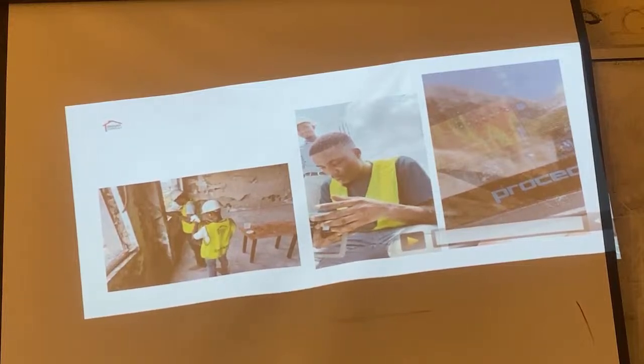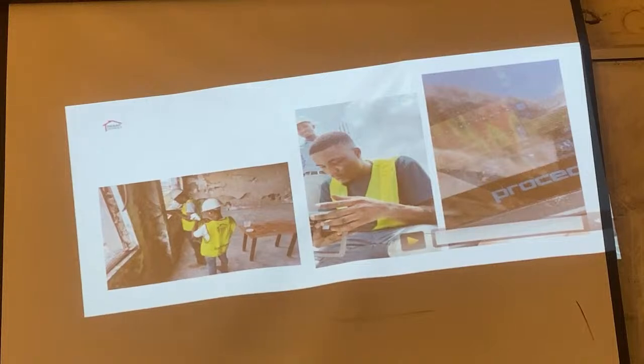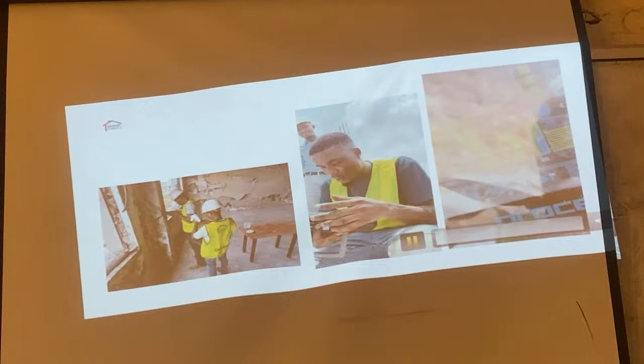I don't think there is any other instrument out there to do that, but NDT actually helps you to just peek through. You can't tell if a concrete has voids or not, because the outside is going to look smooth. But what about the inside? Are there voids? Are there honeycombs? So this machine can actually help you detect that.